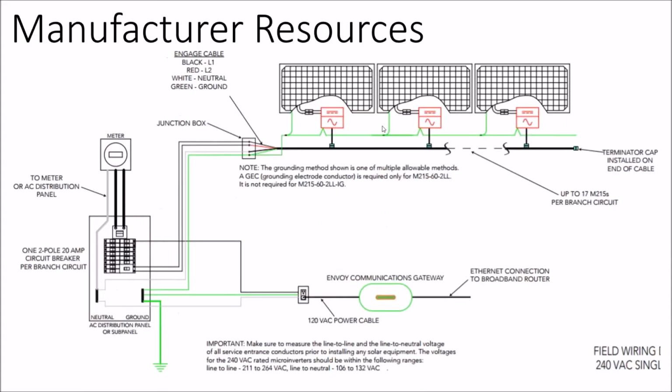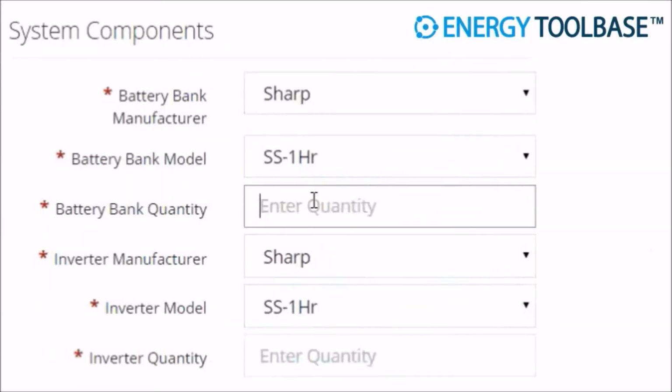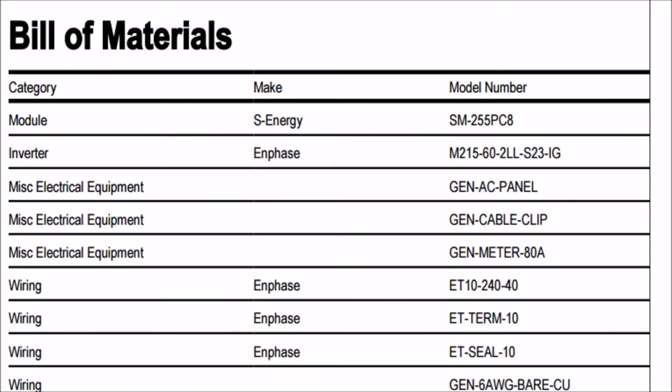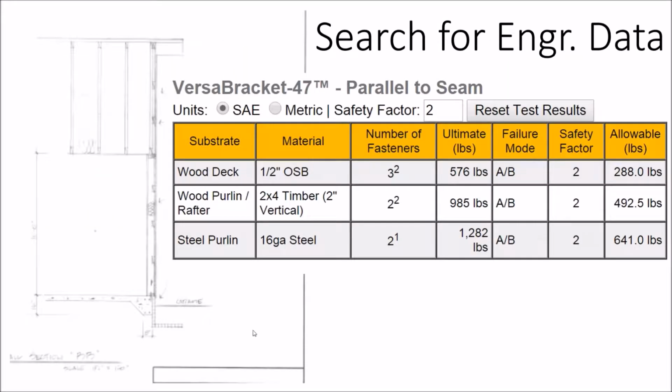And now we're getting into the pull strength of our attachment to the rooftop. And what we see is that the attachment to the rooftop, if we just went into the decking, would have enough pull strength for zone 1 and zone 2, but not for zone 3. And so now we have a better understanding of why the solar designer does not think that decking-based racking systems can work, because they can't work on all portions of the rooftop.